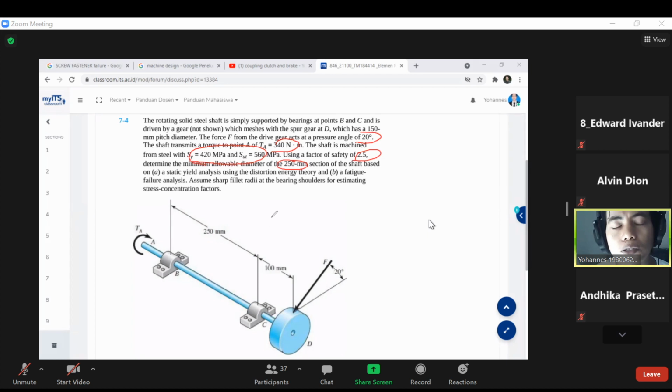Bella, we need the notch concentration factor if we have this kind of shape or geometry of shaft. The notch concentration factor is a function of the geometry change here. So you need information like D1 and D2, and also the radius of the fillet, and the information about the manufacturing process of this shaft. Using that information, you can find the notch sensitivity for fatigue analysis.